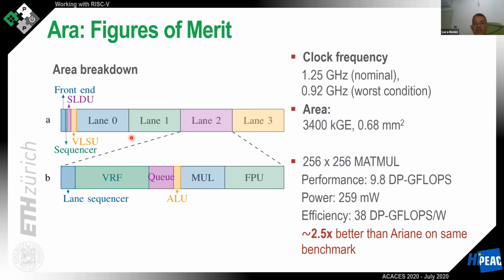The area is fairly big, but this is not a big problem because it's big since double precision floating point multiply accumulate units are big. So you are doing big operations, and as long as you keep these units busy, you will be very efficient. In fact, the efficiency gap, remember, was a factor of 5 with respect to microcontrollers.